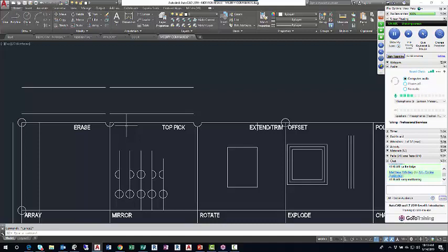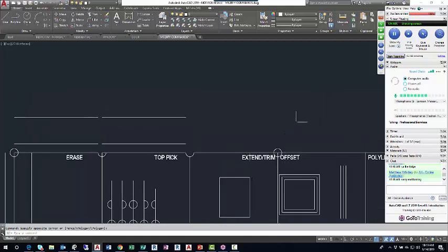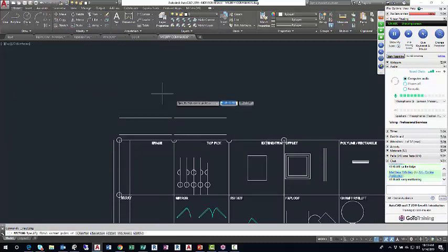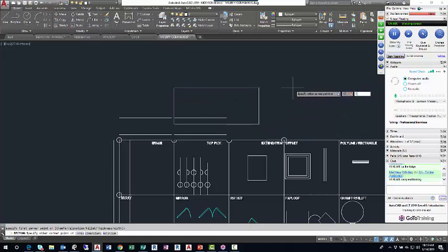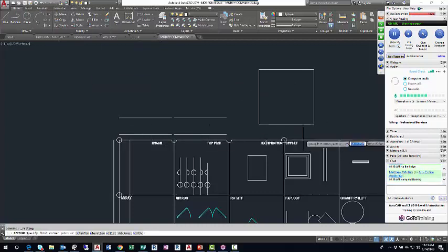My office is about 100 square feet, so it's 10 by 10, which I can draw with a rectangle. I'll go rectangle, left click first corner, 10 feet, comma, 10 feet, enter. And then I've got a rectangle. I keep trying to start rectangle. So right there is my fridge. It's a little dorm fridge, and my desk is about here, roughly.